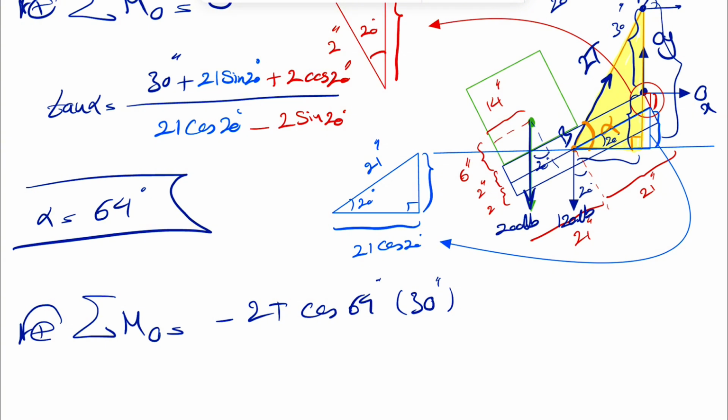And we're going to have the moment of the two weights that we have, one at point B. So let's move on to the moment of the 120-pound weight at point B. I'm just showing that we can resolve it in these two directions because the vertical distance to the line of action is pretty easy. We're going to have the moment of this component, which, as we can see, will be a clockwise moment.